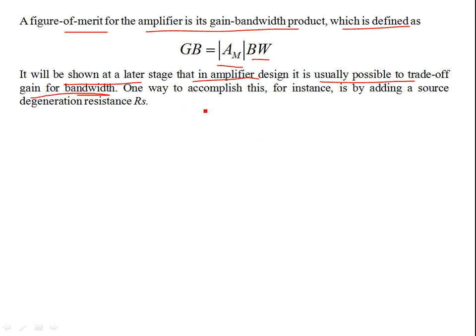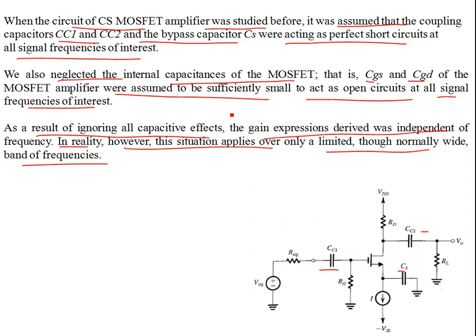For example, if you recall, in our earlier discussion we used a source resistance. If I employ a source resistance at the source point, there is a Vs. If you exclude this current source and use the source resistance, this source resistance tends to stabilize the Q point, owing to variations of physical parameters like temperature that change the conduction parameter of the MOSFET. RS can stabilize the Q point against such variations.